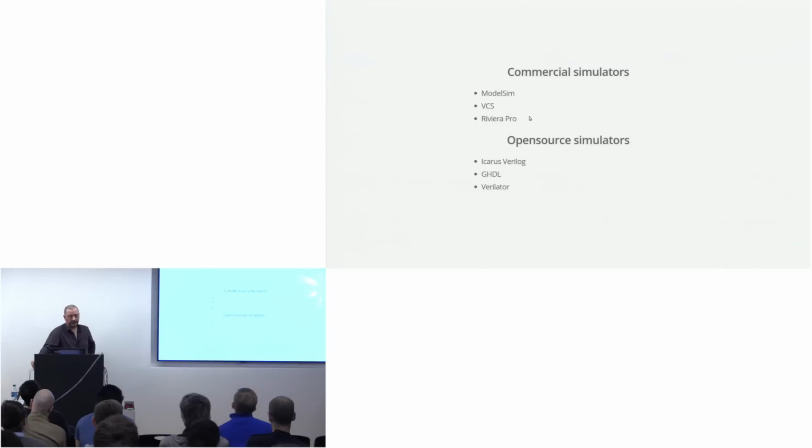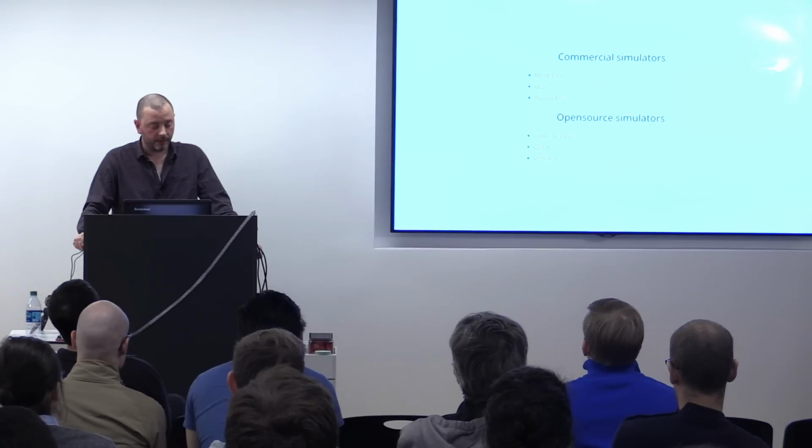And then Verilator, which is a kind of interesting tool that takes Verilog and converts it to a C++ blob, which has been pretty heavily optimized, but with a number of assumptions. Like, you can only put synthesizable RTL into it. And under those assumptions, it can create a very fast model. And that tends to actually get used a lot commercially as well.